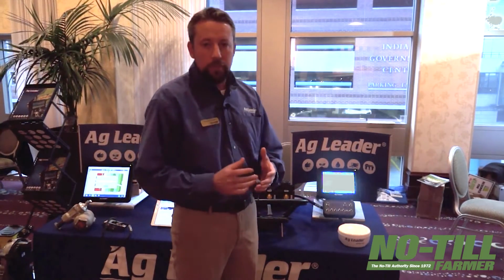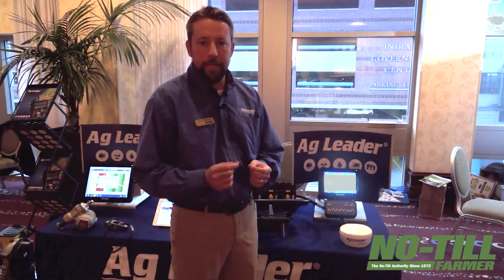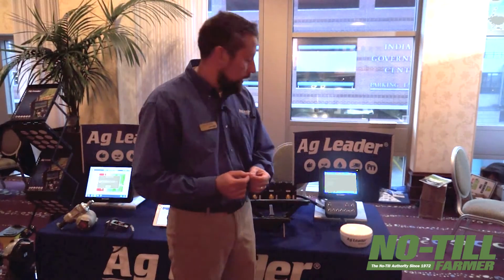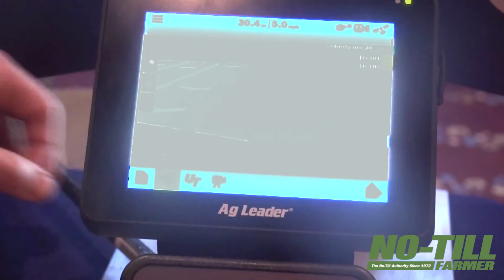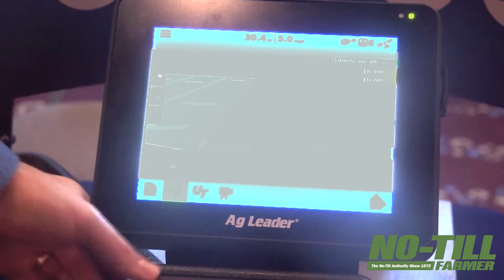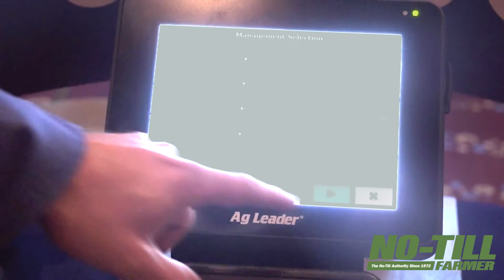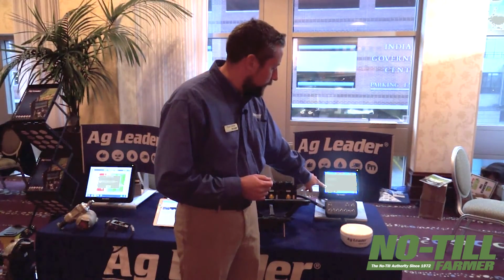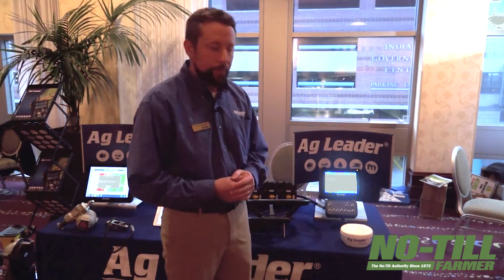And then lastly, we did some enhancements to our liquid control system, and specifically this helps the customer do a better job of spraying, specifically looking at the boom pressure and the droplet size. The system allows us to put a specific nozzle into the system, and then it knows based on the pressure what droplet size we're spraying. Currently we're running a little over 40 psi, and we can see that that's a medium droplet size.